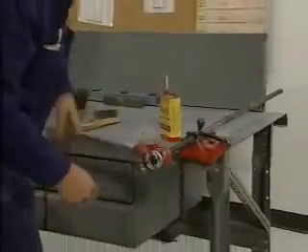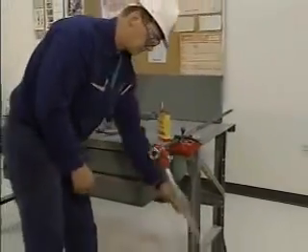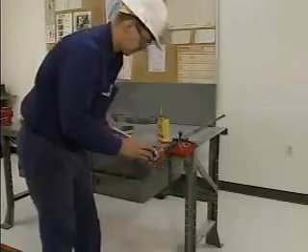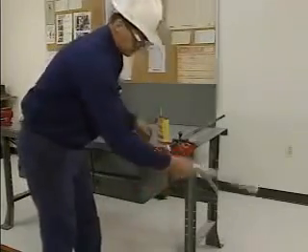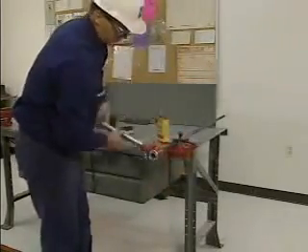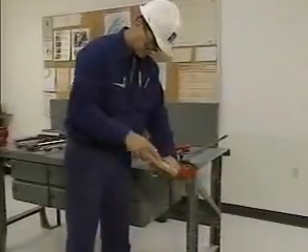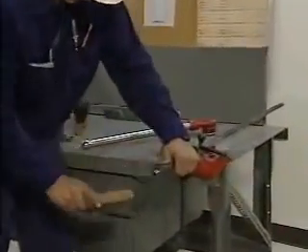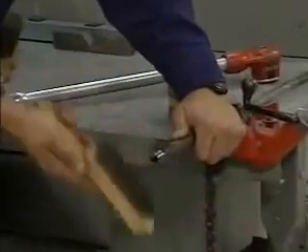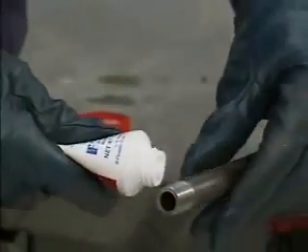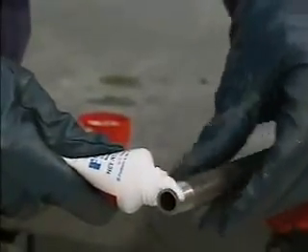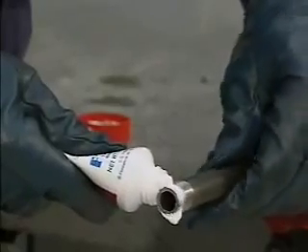It may be necessary to move the die back and forth on the pipe as it is being removed. This removes some of the metal chips and ensures that the threads are not damaged. Now, remove the remaining chips and shavings from the pipe with a wire brush and apply a thread lubricant or a thread sealing compound to the pipe to prepare it for connection to a fitting.